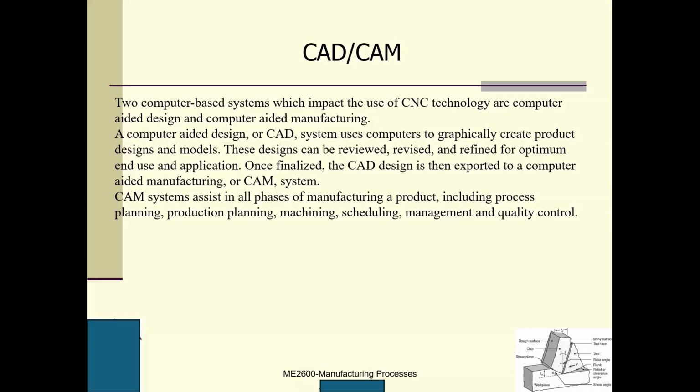When I was at your age, we had three different branches: CAD, CAPP, and CAM. If I know my CAD final product model, and based on what kind of machines I'm going to use, I generate a CAPP, the process planning, which states do milling first, do drilling first, second do turning later.